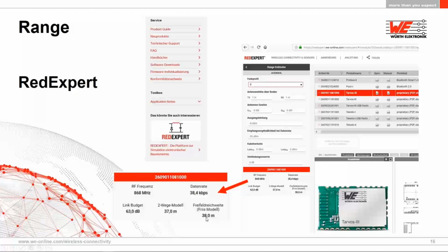But now I ask myself why. Probably because of the TX and RX height above ground, which I entered as 1 meter. Now, if I were to enlarge this to 2 or 3 meters, this difference should become significantly bigger.